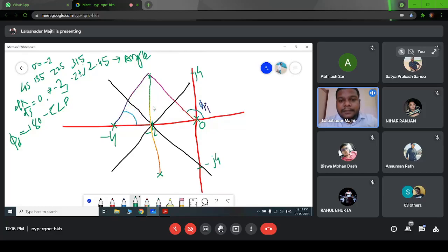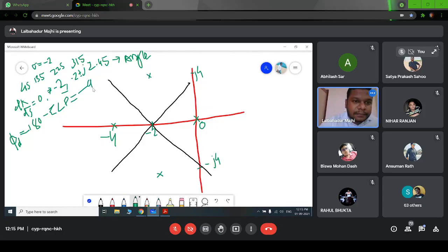So now we have calculated the angle contribution. So 180 minus the summation of angle contribution, we are getting the value to be minus 90 degree for this upper pole. Similarly, for this lower complex pole, it will be 90 degree. Okay, you can calculate. It will be 90 degree. Okay, clear? So we have to draw the line. Similarly, from this it will be 90 degree. So that means the root locus starting from this complex pole will go in this direction. Right? It will go in this direction.